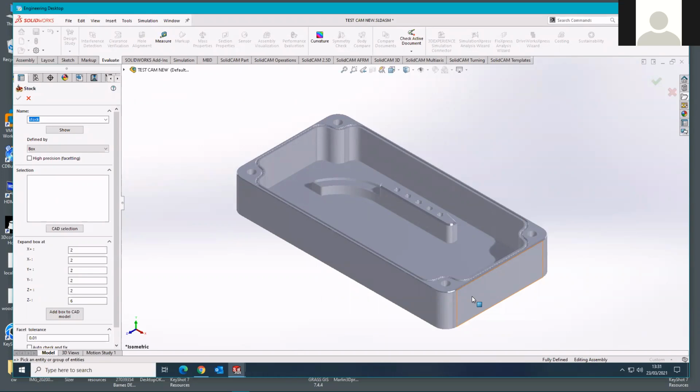So we create a box of material that's slightly bigger than our part to enable us to then trim back using our cutting tools, so that we know the surfaces and faces of our finished part have been accurately machined. We haven't relied on an aluminium supplier to accurately cut their stock material perfectly.